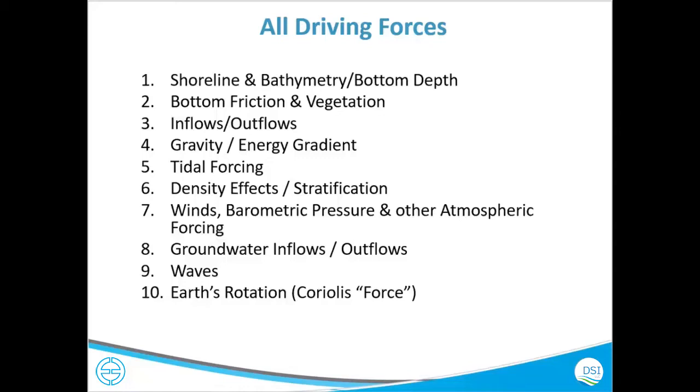You can use all 4, and EFDC Explorer will take chunks based on the distance between the model domain and those stations. So you can have a weighting, for these grid cells you can have 30% from this weather station and 30% from another, and 30 or 40% from another, depending on how you assign. If you let EFDC assign, it will assign based on the distance from the model domain to those locations.